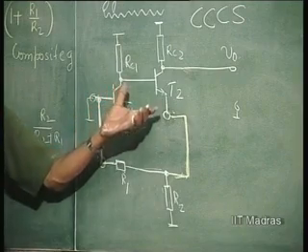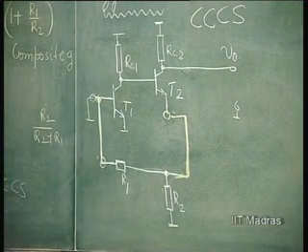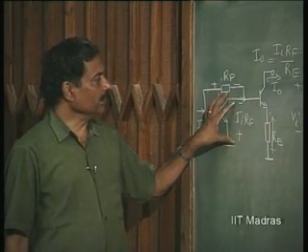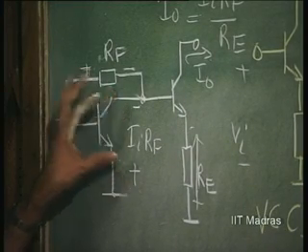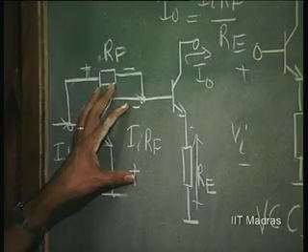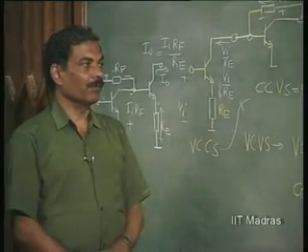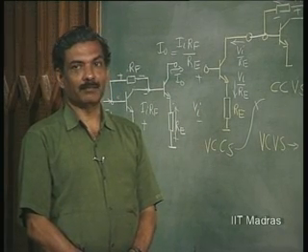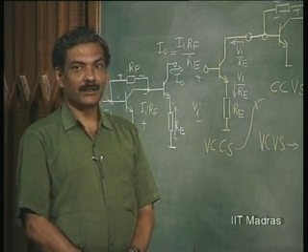So, the sensitivity to active parameter is going to be less in overall feedback structures compared to local feedback structures where the loop gain is just that of the individual stage. So, the sensitivity to active parameter is going to be more here, but we will later see that there is a great advantage in local feedback in terms of trouble free operation at high frequencies, because as you increase the number of stages we get into the problem of oscillations. Negative feedback turns itself into positive feedback beyond a certain frequency and the circuit, instead of amplifying, is going to oscillate. This we will later on discuss.